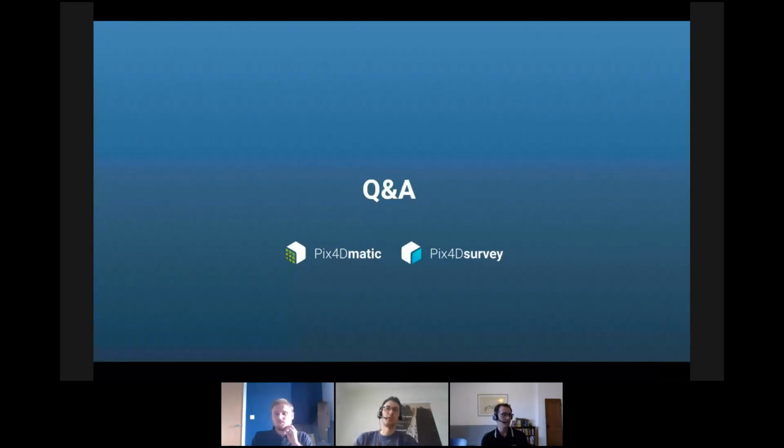So the issue with tarmac roads is that it's really homogeneous, so it's hard to find matches that are really the same point. What I would recommend is in the processing options of Mapper, there are the advanced processing options, and there you can choose how many matches you want as a minimum to be taken into account in the processing. The default is 3. I would go to 4 or 5, which should clean out all the matches that are not as sure as the ones that have 4 or 5, which means that they are seen in 4 or 5 images. So that's certainly a tip I would give you to improve how good it looks.